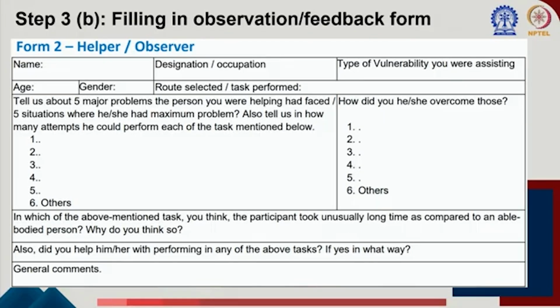A smooth surface without any ups and downs looks barrier free. But if that is a 50-meter long corridor, then that is not barrier free, because the person will be tired at the end of maybe 30 or 40 meters and would require to sit. So that's why the simulation exercise is important, to understand where exactly the shoe pinches.